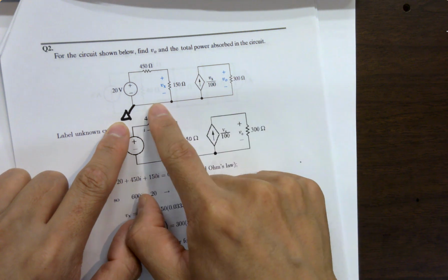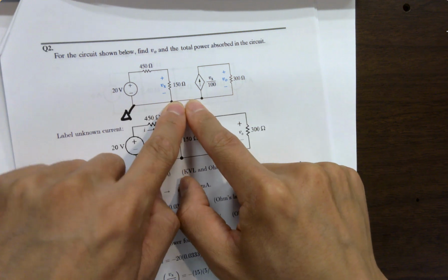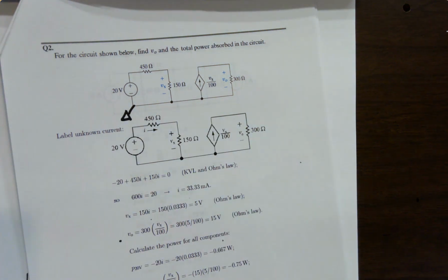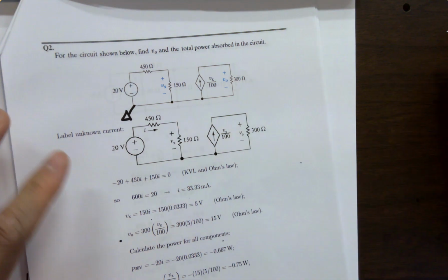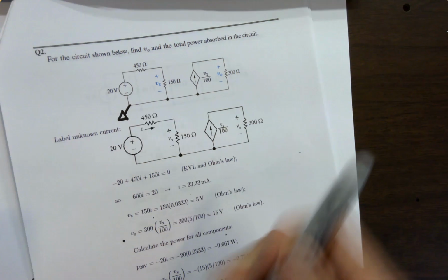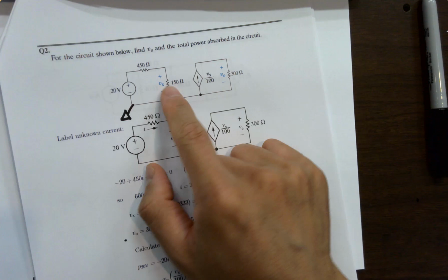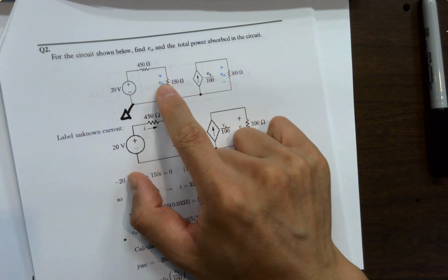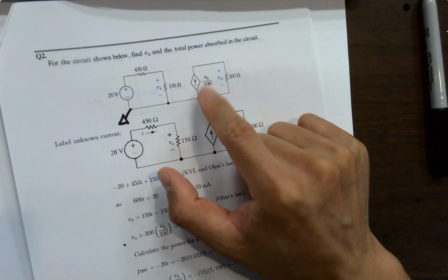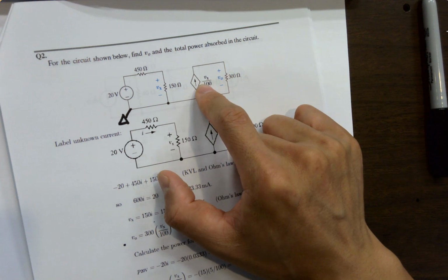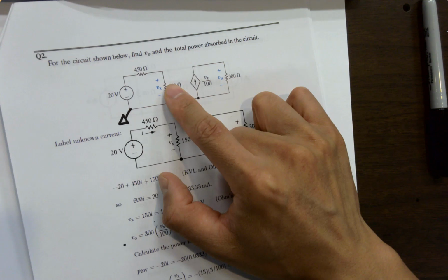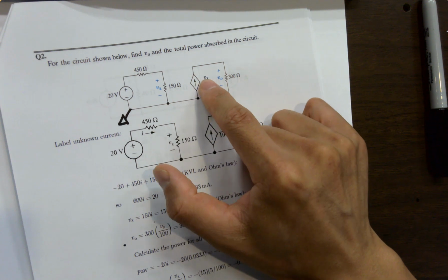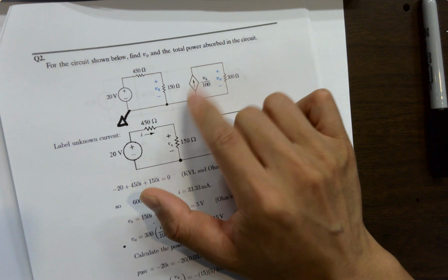Why? Like I said, it's the one voltage node. It's one wire. You can always imagine that you can heat it up and melt it, so it becomes one joint. It's just one metal wire, just one metal piece. So what's happening is you see Vx, for some reason, it could be some magical electromagnetic field. Vx here is affecting the current here. So this current source becomes a voltage controlled current source. It's an arrow, so that's why it's a current source.